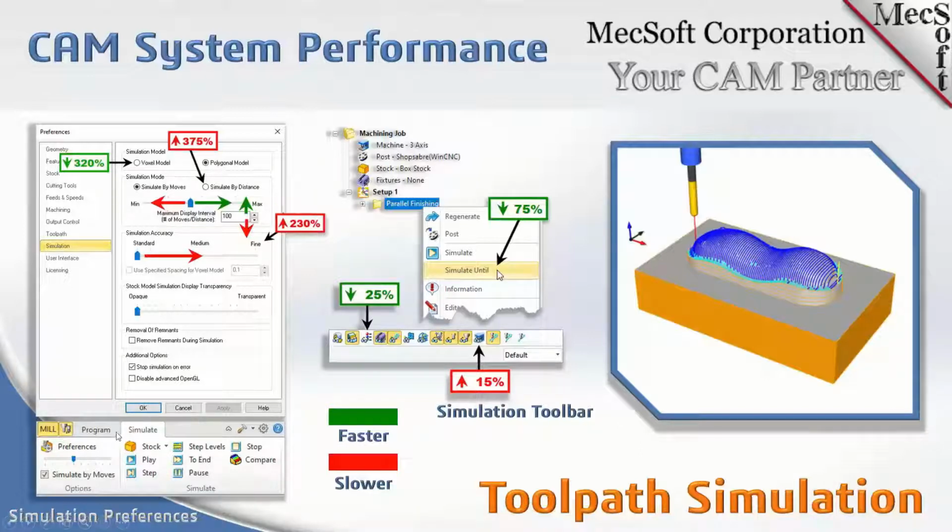If you look down here on the simulate tab, there's a checkbox for simulate by moves. Using the default parameters, check simulate by moves and that will be faster. You also have a slider here that relates to the slider down here on the dialog. It adjusts how many times the model is being displayed on the screen.